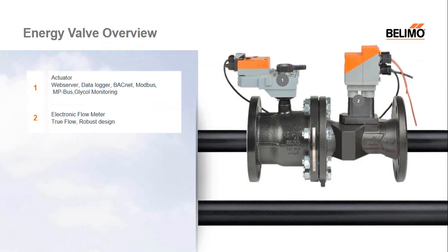It's an ultrasonic transit time design, a very robust design with no moving parts, like a paddle style wheel that could become clogged with debris over time. So it's a very robust and accurate design.